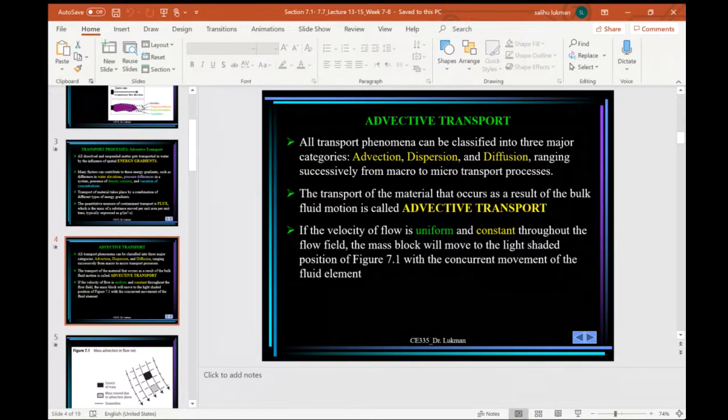More often than not, we need to understand transport first in an open channel very well, and then we scale it down. What about if we have porous media inside? How does the porous media affect the transport mechanism? We have just seen previously under chapter 5 that we have Darcy velocity and the seepage velocity. The seepage velocity is higher and different from the Darcy velocity.